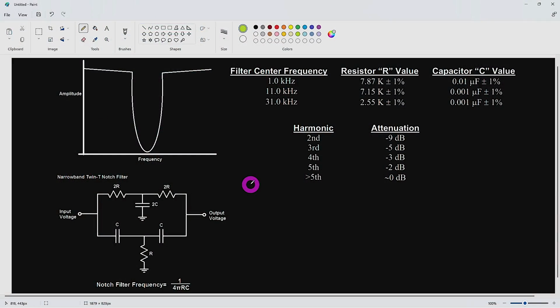So if a direct measurement is not possible, we have to do an indirect measurement. And we're going to take advantage of a similar technique that the instrument does to improve the THD. We're just going to do it the other way around. The instrument uses a filter to get rid of the harmonics. But in this case, we're going to build a notch filter to get rid of the fundamental. By choosing the values of these resistors and capacitors appropriately, we can tune this filter such that the fundamental signal will be right in the notch.